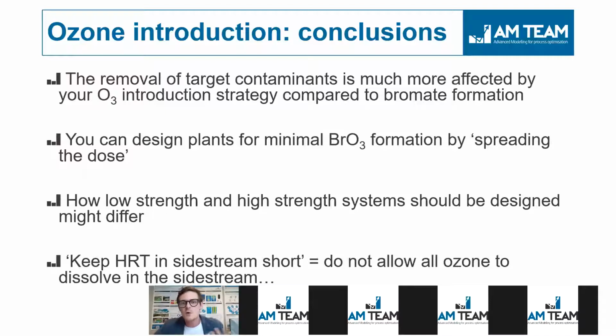In fact, there is also a lot to do, as we as practitioners know, about side stream versus bubble column. Yes, there are differences in costs, in maintenance, pros and cons for each, but there are differences potentially in bromate formation as well. I'm not saying that side stream is inherently leading to higher bromate formation. There are side stream systems out there that produce very limited bromate. But if you talk about keeping the HRT in the side stream short, because that's the general guidance, if that is too long, your bromate goes up very, very fast.